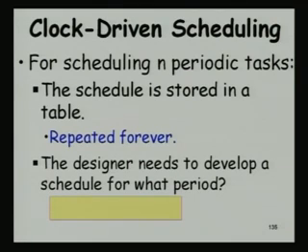Yeah. So, we are assuming that the tasks start in phase, and for again the similar condition to occur, right, we have to look at a multiple of them, that is the common multiple, and we take the lowest common multiple. But what if the tasks do not start in phase? We said that, see, when they start in phase, different tasks are there.